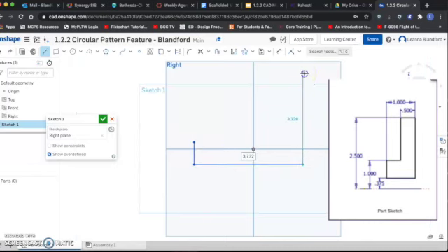You'll note that I am staying away from the origin lines because they tend to make things act a little funny. I got really lucky that time and was able to connect them without trimming. At that intersection, you're going to want to make sure you get an even and straight line before you move on. Now I need to dimension this.